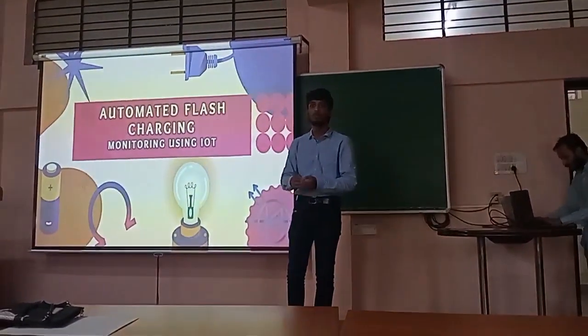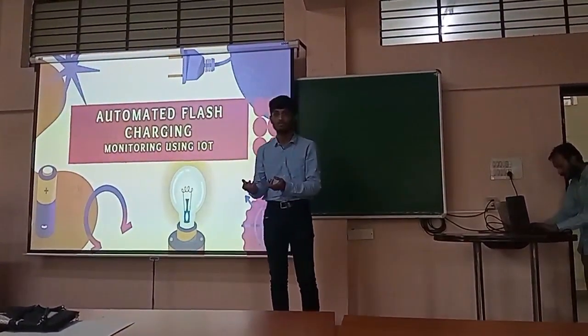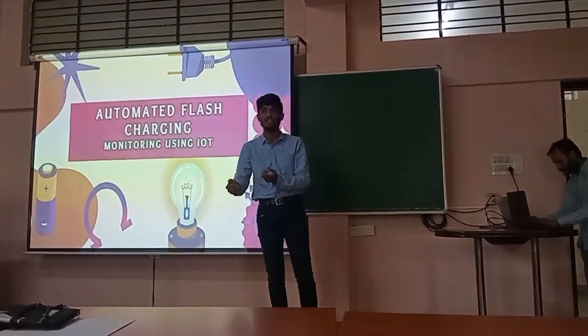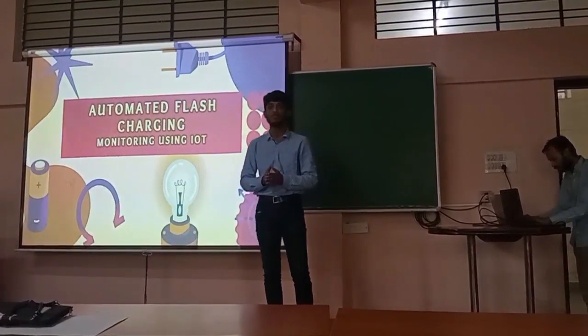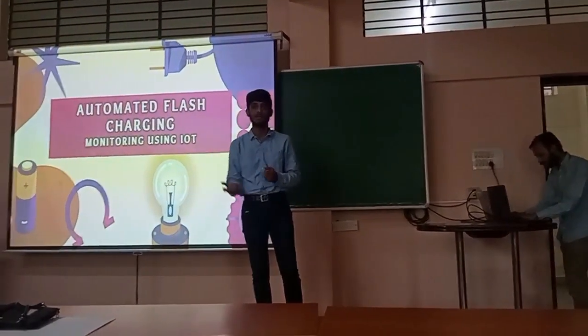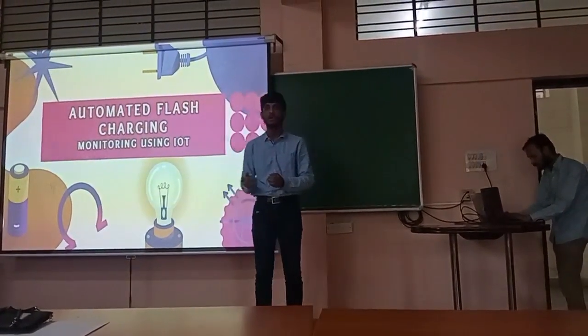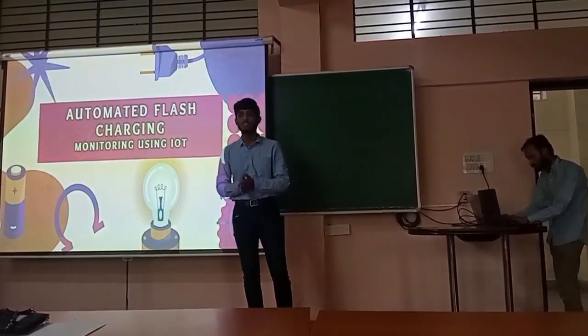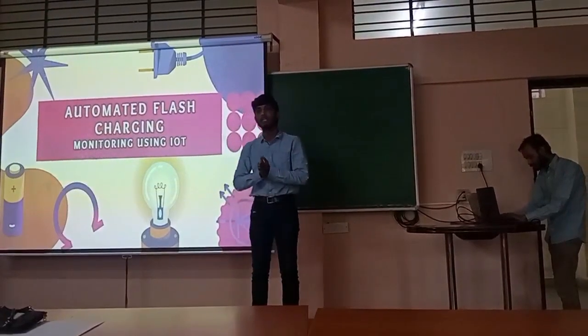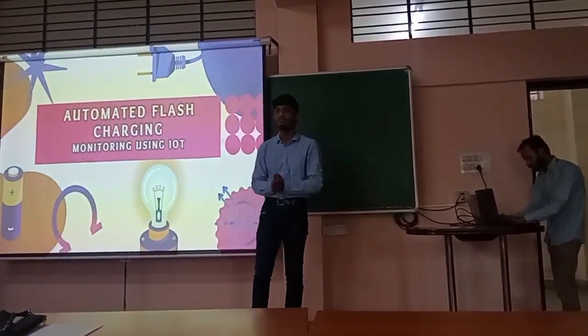It can't take up so much of the regenerative power which is coming out of deceleration from the vehicle. Also, it can't handle fast charging to very great extents, which degrades the battery life. Also, there is a risk of fire. There are so many catastrophic accidents happening with lithium-ion batteries deployed in electric vehicles.